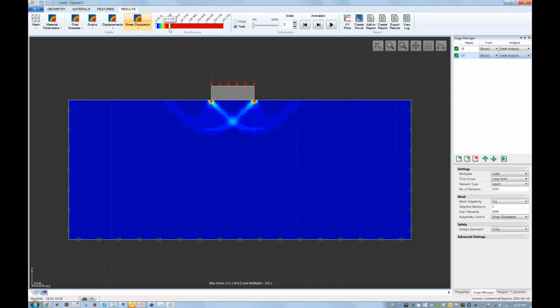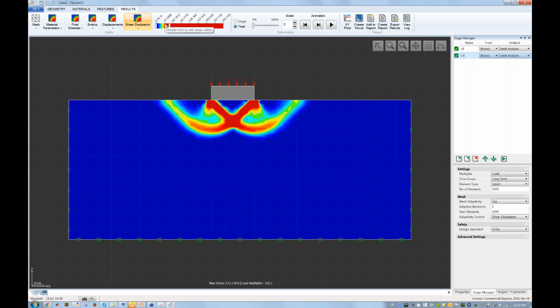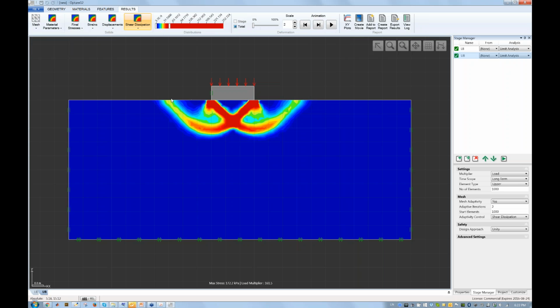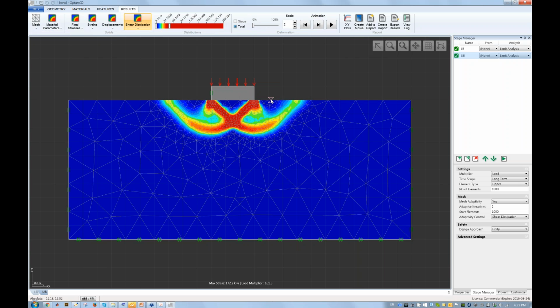is. You can of course use even more elements and more adaptivity iterations to get an even more accurate solution, but with this error that we have now, we would somehow think in most cases that would probably be all right. To show you the adapted mesh, it's shown here, and that of course captures the solution. The slip lines you can see have become much more distinct now as a result of the mesh adaptivity.